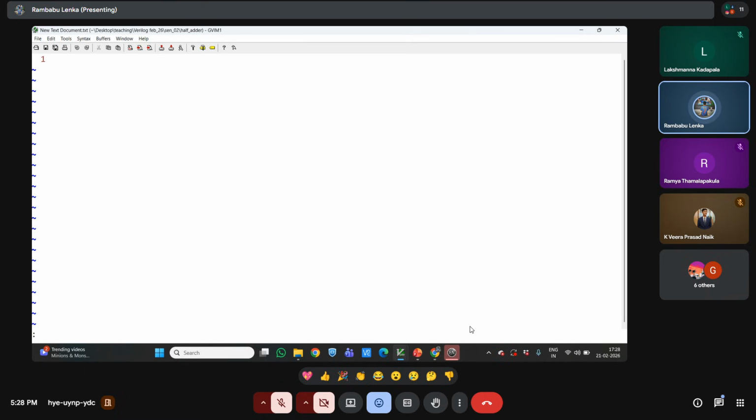Yesterday I told you that two files will be required, design and test bench. What is the first one? Design file, tab new. This is my design, half adder design, design.v. Now enter. This one close. Next, my test bench file is required.